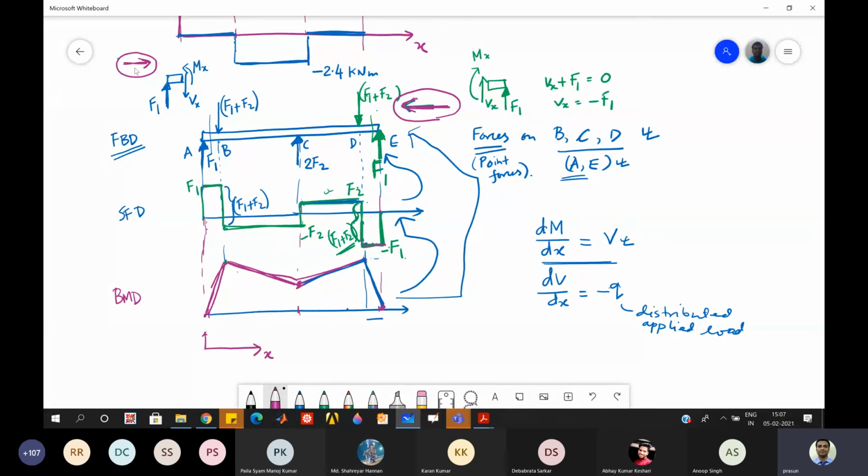No, so that you see why I told you, because when you draw a cantilever beam, how you represent it? Generally we represent a cantilever beam by a support here, right? And then for a cantilever beam, it is always better to go from this side, because even you can draw, let us say there is a force P. If I tell you to draw the shear force and moment diagram without finding this reaction, you can draw the shear force diagram by taking the cut section and taking this one, not this one.